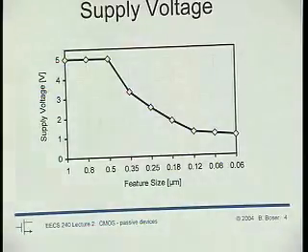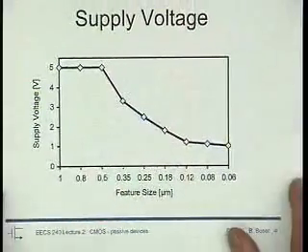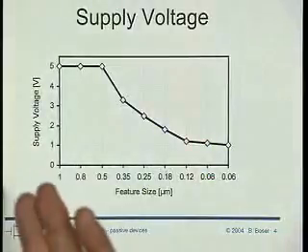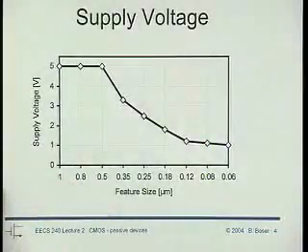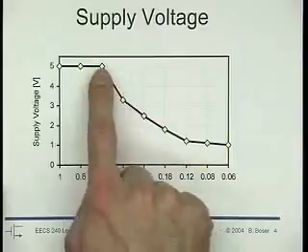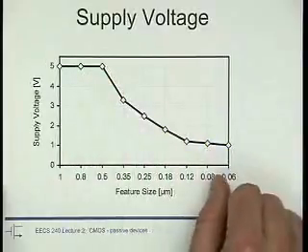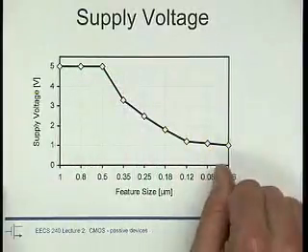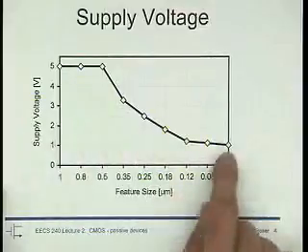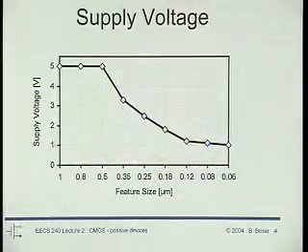Well, the 0.35 micron model that I have on the website, and on the website it's sort of free for all. You can get it. So that's sort of one practical thing. The other thing that is even more important, and you will appreciate that when you do homeworks, is that as we scale down device channel lengths, the technology side, we invariably also see the supply voltage go down.